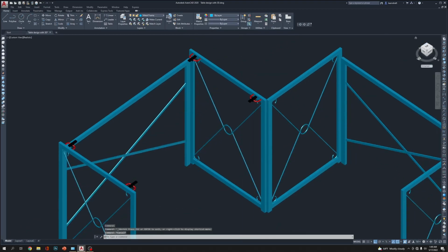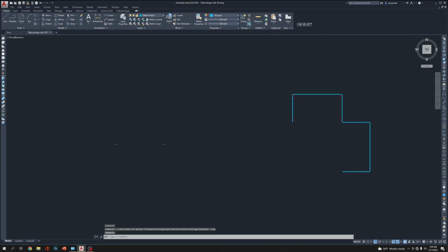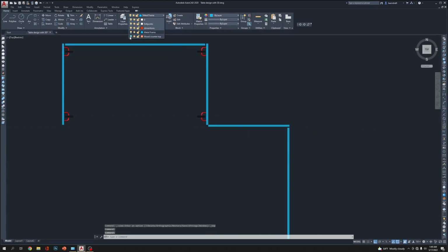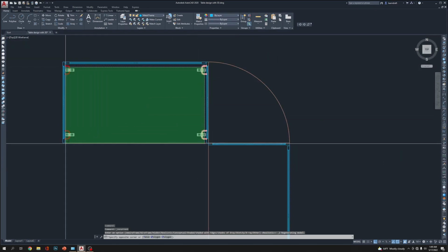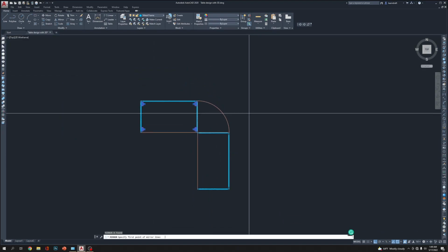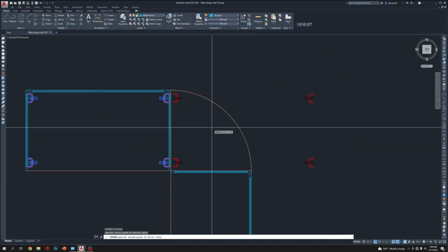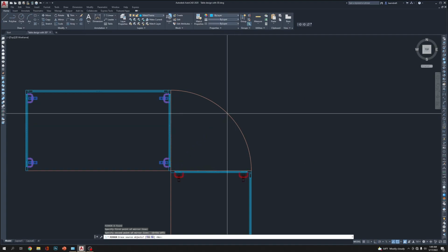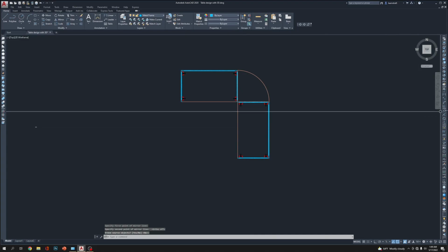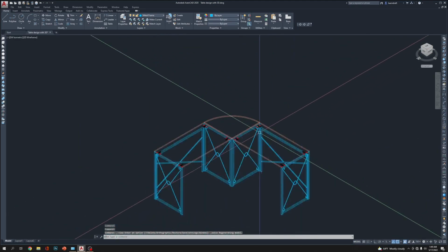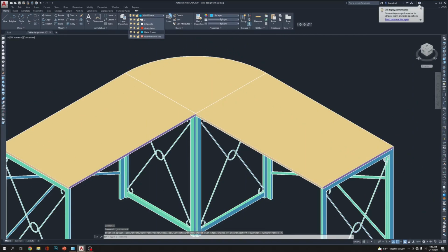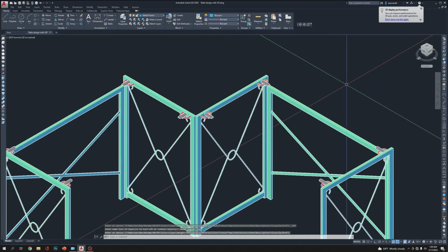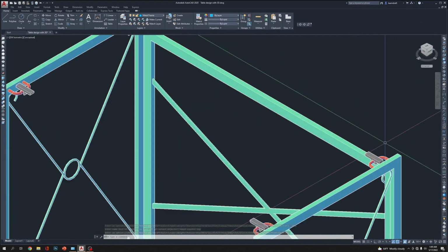So this thing should be on the other side. Other side means here. So I'm going to bring back my wood, go to the wireframe, select 4 of these, go to mirror, click from this corner, F8 to the other corner, enter, and it gets copied everywhere. I need to go to the isometric view, zoom in, take a look fast like this, take out the wood, you have your metal there, but this plastic should go with the wood.